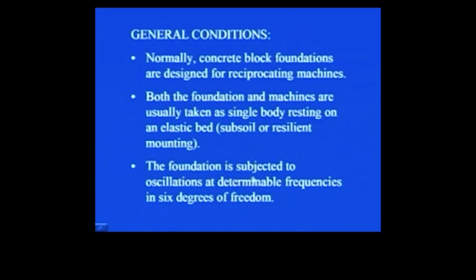The foundation is subjected to oscillations at determinable frequencies in 6 degrees of freedom. We have already seen that there are 6 degrees of freedom, that is the translation along x axis, y axis and z axis, and then the rotation about x axis, which we called pitching, then rotation about y axis, which we called rocking, and then the rotation about z axis, which was called yawing.